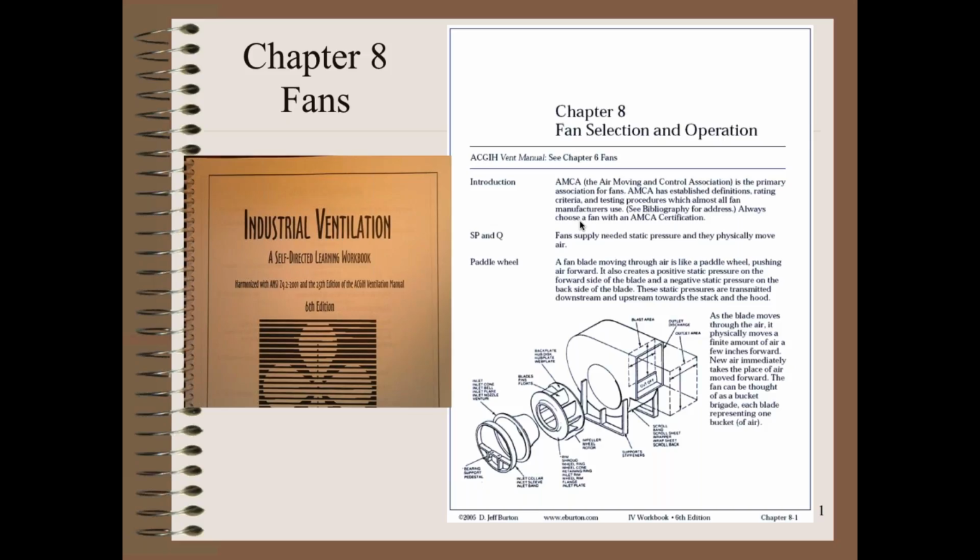So if this is zero static pressure over here, and you go out 10 feet with 12-inch round ductwork, how much of an impediment to that flow does that 12-inch round ductwork give you? 10 feet. You calculate it the same way as you did on the suction side. You can look up K for galvanized iron ductwork, or you use that table 5, and you figure out, okay, well, the K times the velocity pressure, how fast the air is moving through here, let's say that's half an inch. That's at this point here, you have to have plus half an inch in order for it to go through that ductwork.